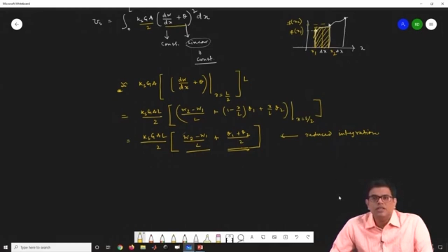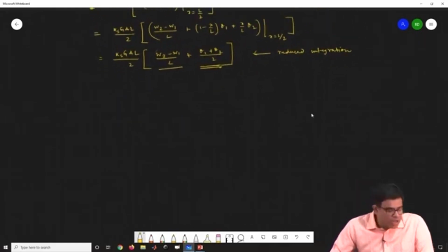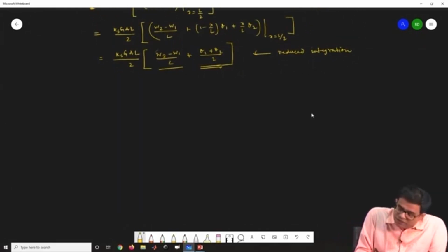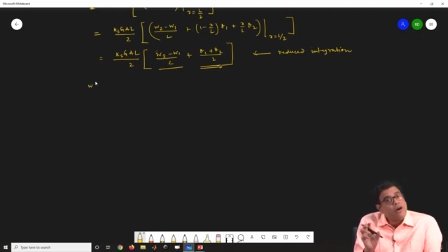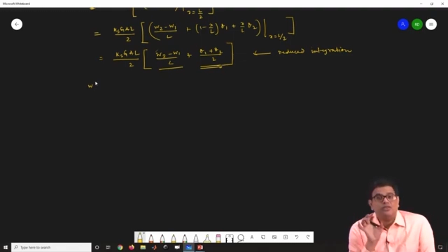What I will do now is calculate the stiffness matrix. The advantage of this is that our finite element stiffness matrix will still be 4x4 here, because we won't have a 5x5 matrix, which we observed in the earlier case, even though we can reduce it with the elimination of the mid-node displacement variable.